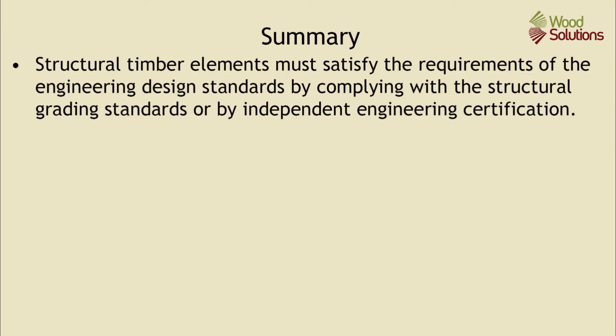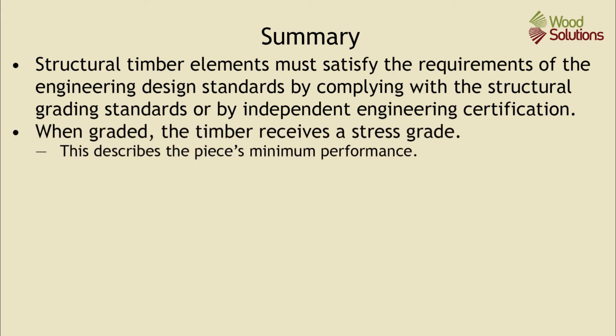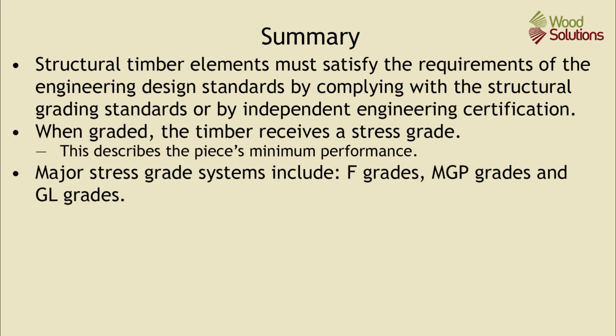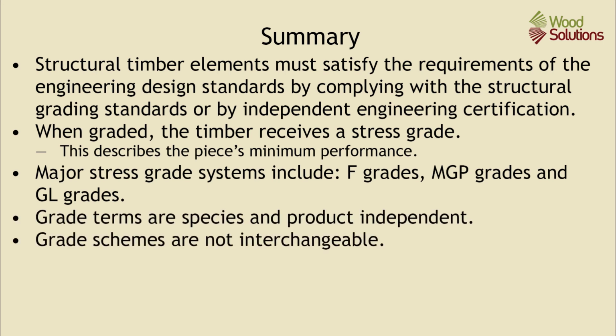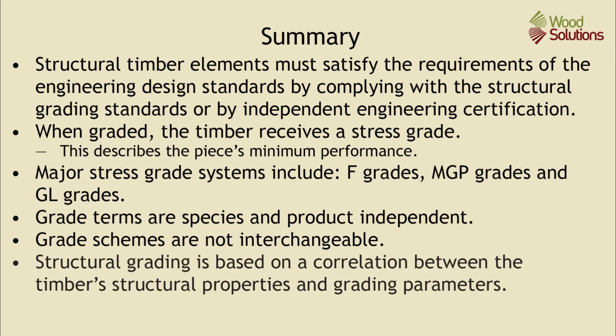In summary, structural timber elements must satisfy the requirements of the engineering design standards by complying with the structural grading standards or by independent engineering certification. When graded, the timber receives a stress grade. This describes the piece's minimum performance. Major stress grade systems include F grades, MGP grades, and GL grades. Grade terms are species independent and grade schemes are not interchangeable. And structural grading is based on a correlation between the timber's structural properties and grading parameters.